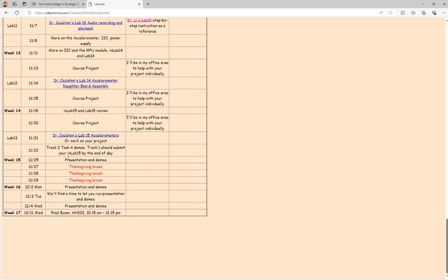Okay. So I haven't fixed your board yet, but other people also requested the PCB. I left a comment in Canvas saying you may have minor issues with your PCB design, because most of you have very common issues. For example, the trace width is too thin, which is going to introduce a lot of resistance, and the density is too low. You can make a board footprint 2 times smaller, but eventually it just becomes bigger.